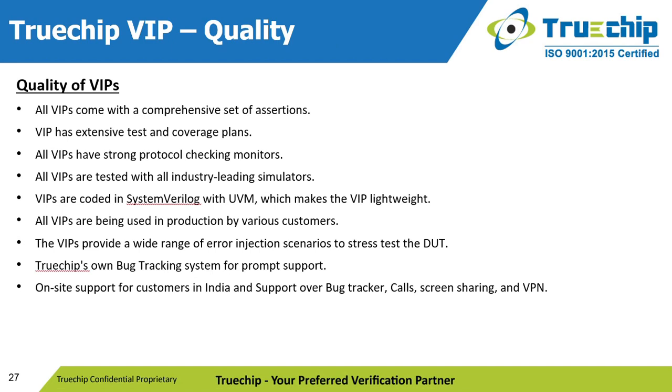Quality of VIP. All VIPs come with a comprehensive set of assertions. VIP has extensive test and coverage plans. All VIPs have strong protocol checking monitors. All VIPs are tested with all industry-leading simulators. VIPs are coded in SystemVerilog with UVM, which makes the VIP lightweight. All VIPs are being used in production by various customers. The VIPs provide a wide range of error injection scenarios to stress test the DUT.